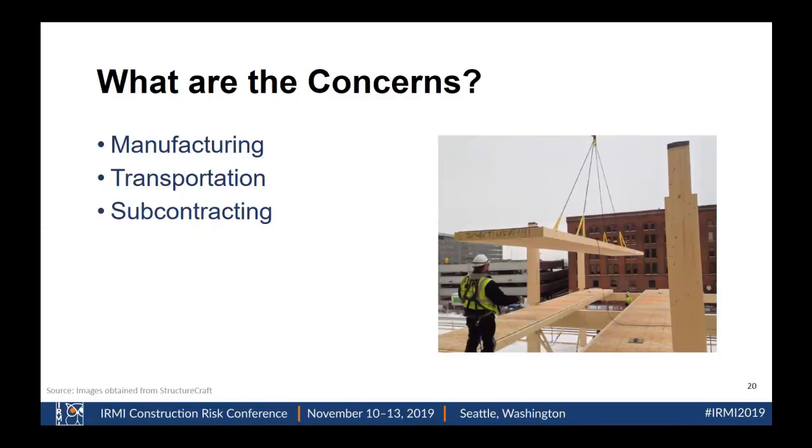Subcontracting was difficult as you're a pioneer, but we actually self-perform the erection, and the simplicity of it isn't quite known yet, but it's very simple to erect it. And right now we're considered the leading expert in it, which once people get a grasp of it, they'll realize that it's easier to erect than steel because you don't have all of the welded connections. It's just lags, screws, and then some protective measures that you put in place that we'll talk about in a little bit. Water performance is something you definitely got to be aware of and you got to protect.